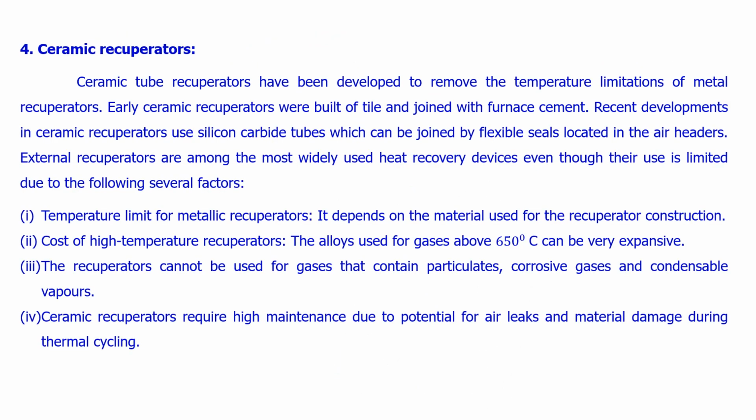Ceramic recuperators are the fourth type of recuperator. They overcome the limitation of metallic recuperators. Here the ceramic recuperators were built to join with the furnace cement. The temperature limit for metallic recuperators is around 650 degrees Celsius, the exhaust gas temperature.